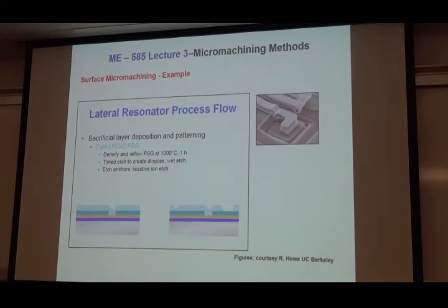Now remember, this is a sacrificial layer, which means eventually I'm going to get rid of it. So it's going to give me a gap of 2 microns for my moving parts. And that's why I'm going deep.